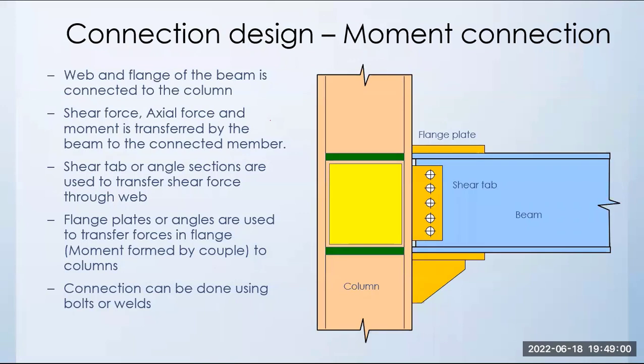How can you decide the purlin section, on which basis? Purlin section, Z section, is based on the loading or spacing of the beam. So first we have to find out the loading. Based on the loading, we have to decide the purlin sizes.